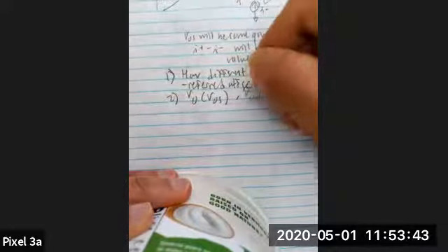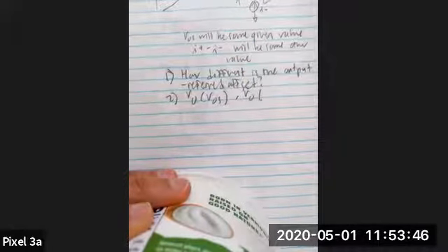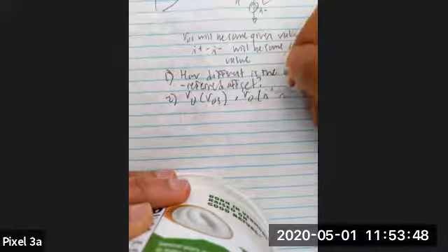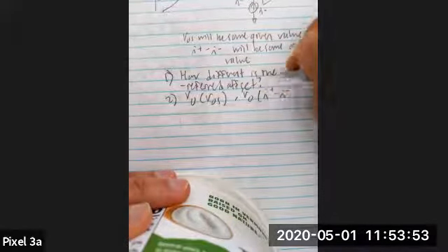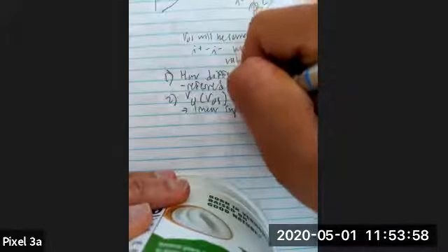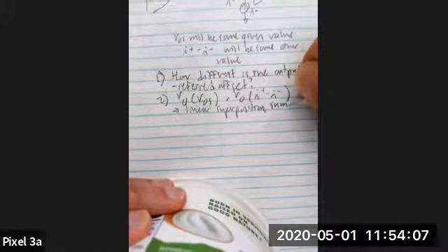To do that, we find V out as a function of VOS, and we find V out as a function of I plus minus I minus, noting that we can do this via linear superposition. So zeroing out the sources that we don't want to analyze at any given point, and then we can add at the end.